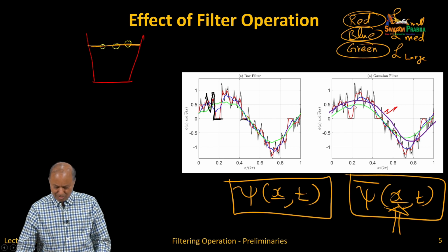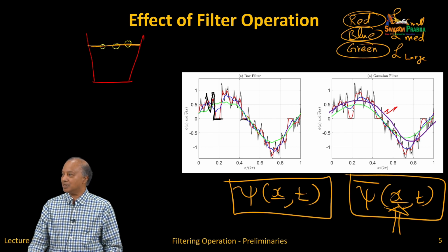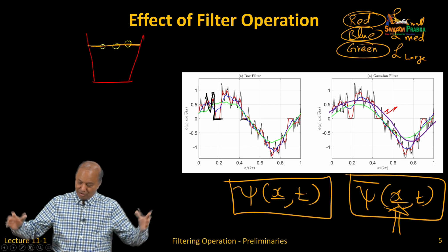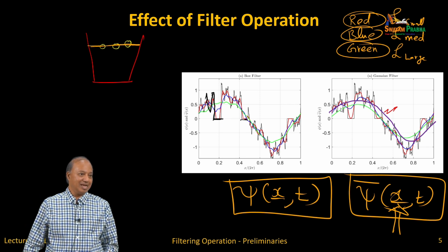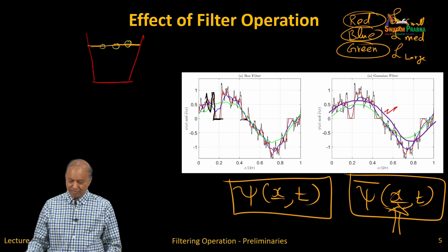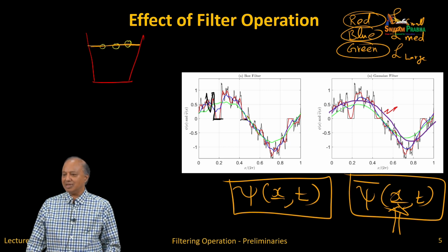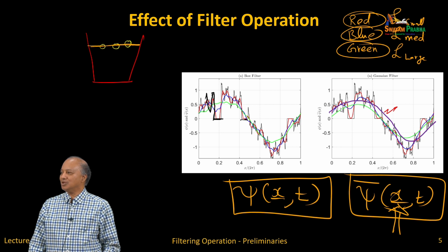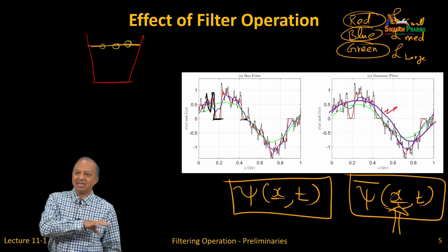If you then decide to do a broader filter, then the blue line may require more modeling because more turbulence is being modeled. If you choose green, much broader, you have to model even more. In RANS, you have to model every bit of the turbulence, and therefore the models are much more sensitive. The other thing you may all know in LES is that if the filter width is in the inertial range, then it is easier because inertial turbulence is easy to model, and therefore you may get universal models with LES, but in RANS you may have to fine tune your modeling. So there are advantages and disadvantages.